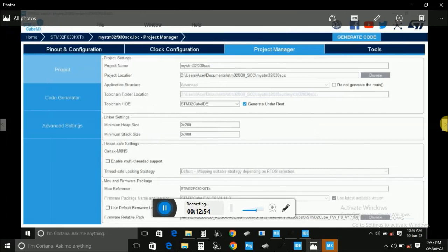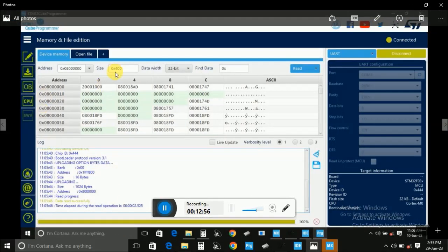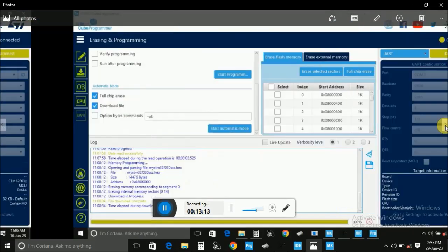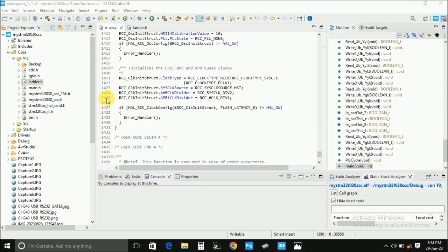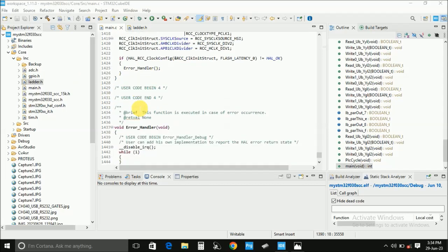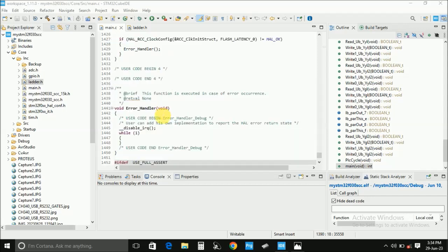These are the settings that I did, and this is what the programmer will produce using the Cube Programmer. And you can see the chip there being identified, right? It works wonders, and it looks ugly, but it does the job. Okay, so coming to the code there, you see the C code that you have to adjust. I'll show you where you need to adjust.